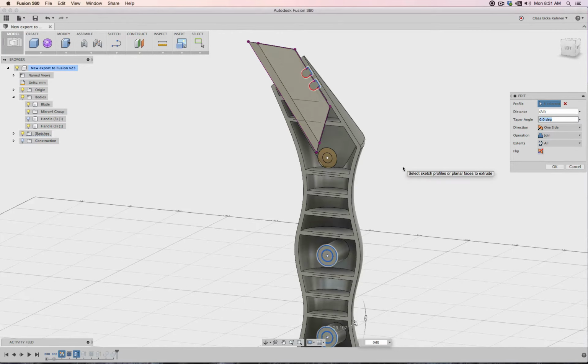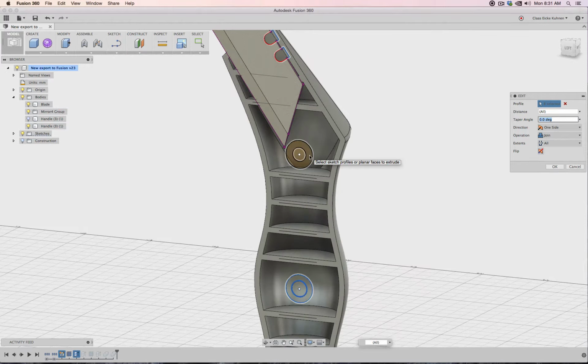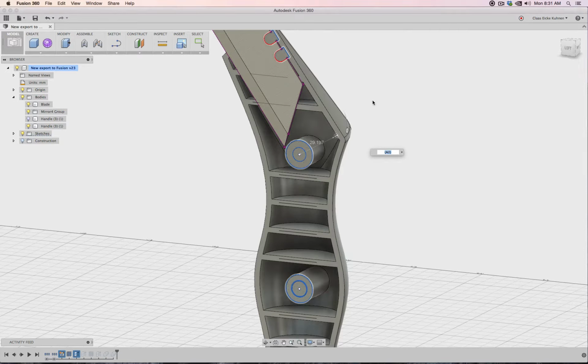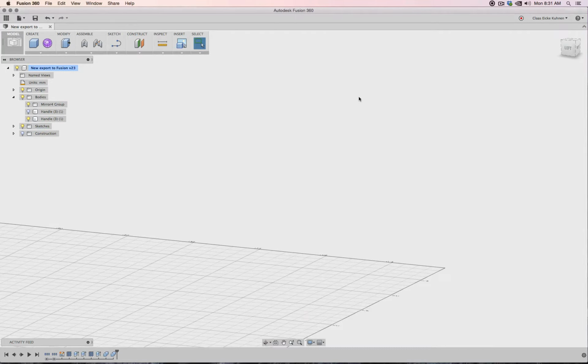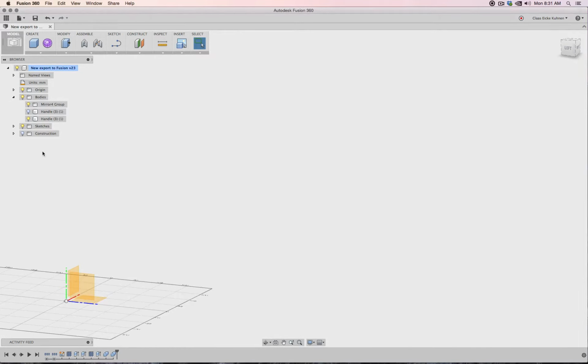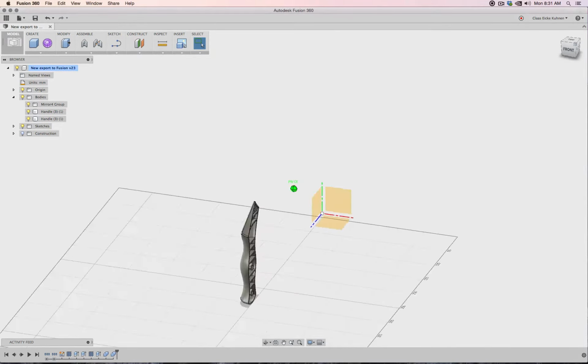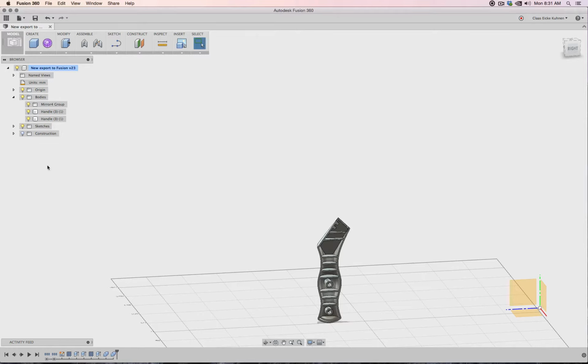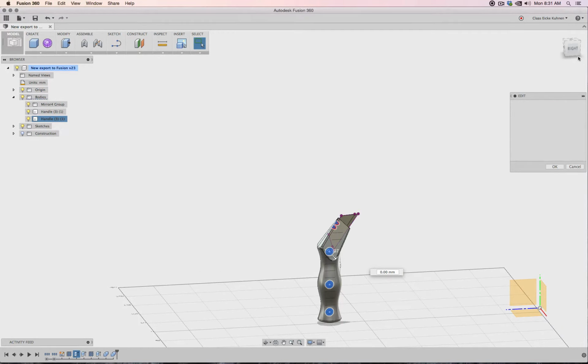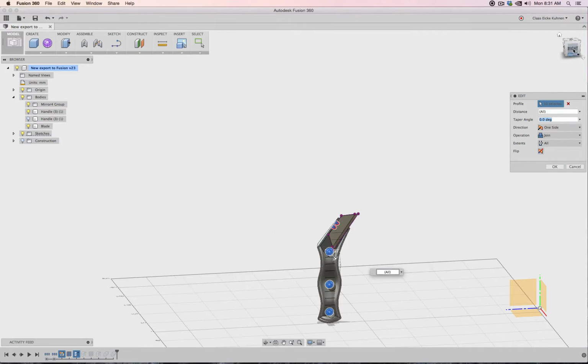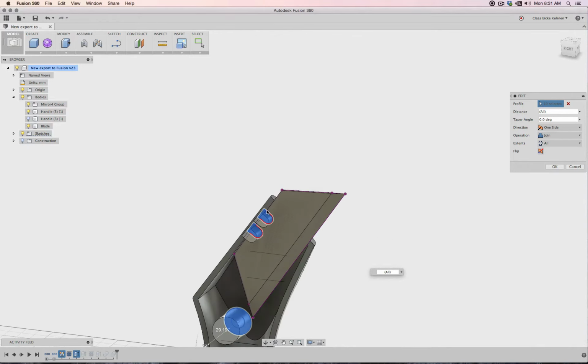And then what we're going to do, we're going to add this one actually to this part of the shell. Okay. And there's another problem that happened actually right now. Oh, where did all my design go to? So you see actually that some of my stuff is gone, and also of the blade. So when I go back to edit here and let's hide this one shell so you see what's there. The problem is that I'm joining those extrusions to the body, and then also the knife, or the blade, is next to it, so it fuses everything together.